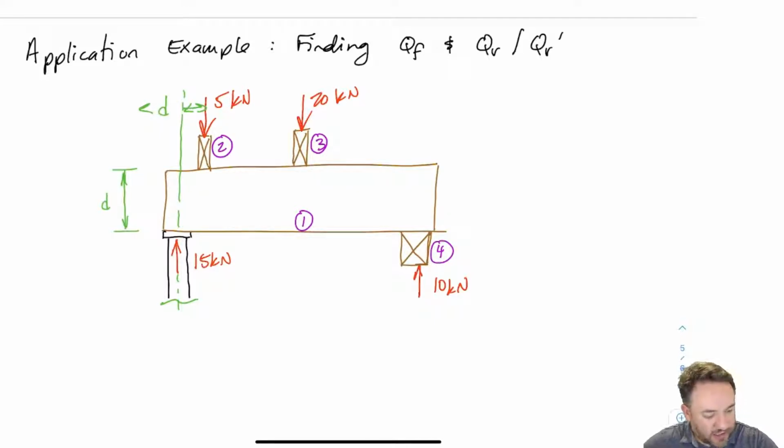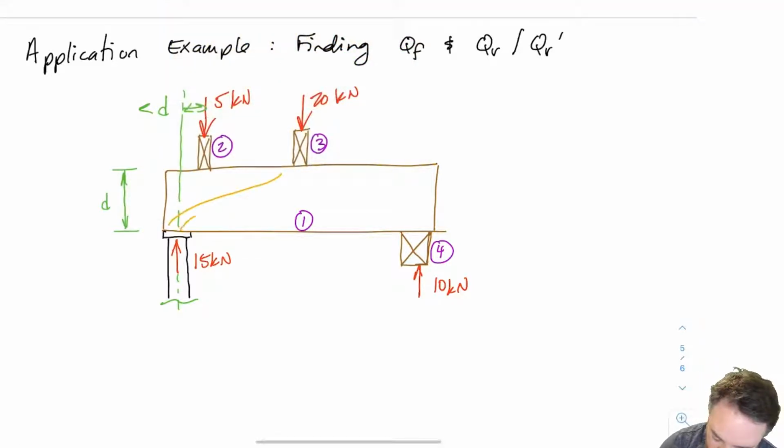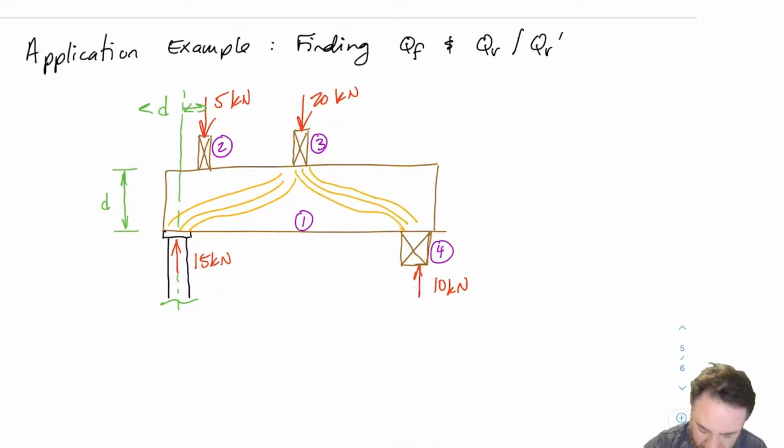And I want to find out all of the different bearing checks that I would have to do for this assembly. So there is bearing of the joists on the beam. Then conversely, there's bearing of the beam on the joist. So the joist applies a load to the beam, and the beam conversely applies a load to the joist. So there's bearing checks for both directions there. And in addition to that, we have our regular kind of bearing check due to the localized compression perpendicular right below the member. But we also, in this case, have a through member squeezing bearing check for the joist on the left.